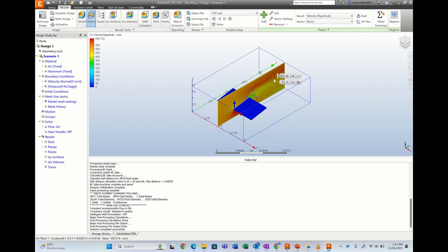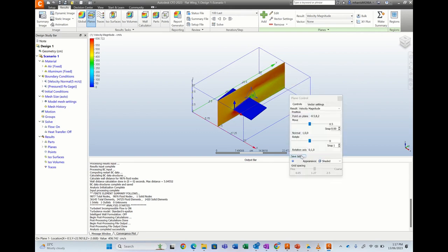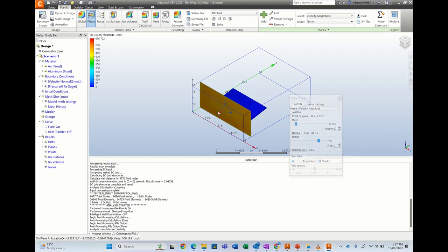The other thing that we're going to do is to rotate this plane. All right, so we select on the plane, and then we select onto this little control here. And we're going to select on rotational axes. And we want to go the z-axis, want to give that a 1, want to give y 0 and x 0, and then OK. And in here now we can just select 90 and select anywhere, should be even here, and it will rotate. We're just going to get on the blue arrow here and sort of drag it forward. It's gone too far. Oh, here we go, back on the arrow, move it back here, there we go.